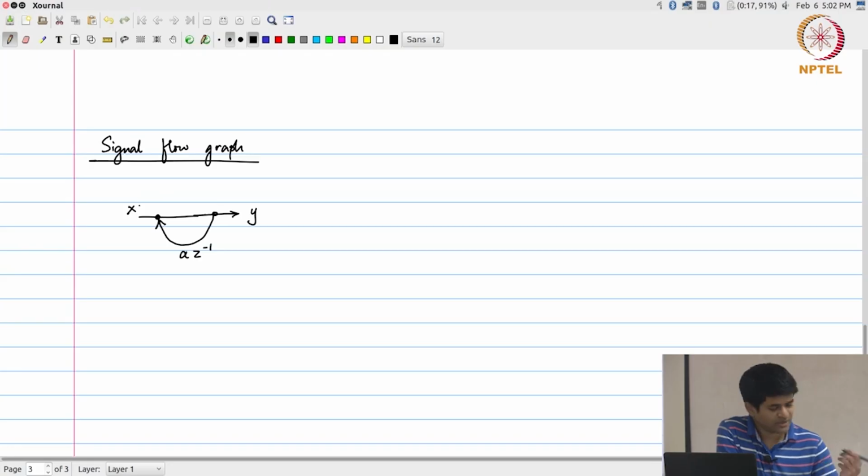Okay, which means basically that we could eventually come up with this. And also any time that there is a junction, this indicates addition, and this is a branch which basically indicates a splitting of the signal. It's not that half the signal goes here, half the signal goes there. It just means two copies of the signal, right? The same signal is fanned out to two different places. Okay, so you have junctions and branches and these arcs.